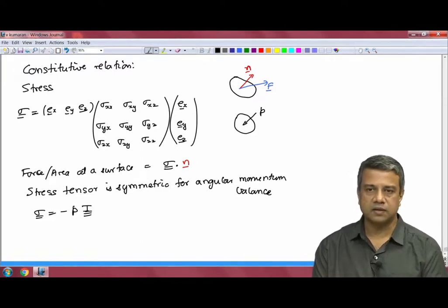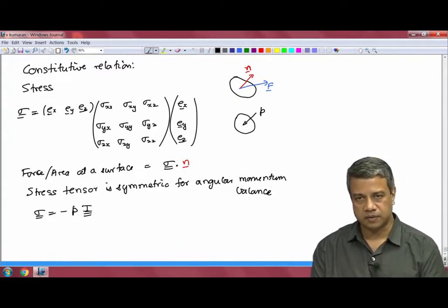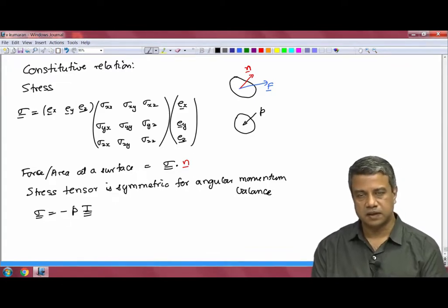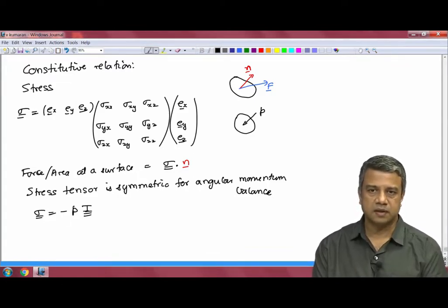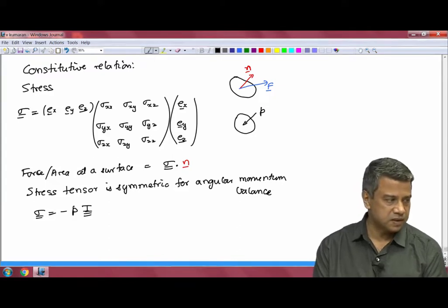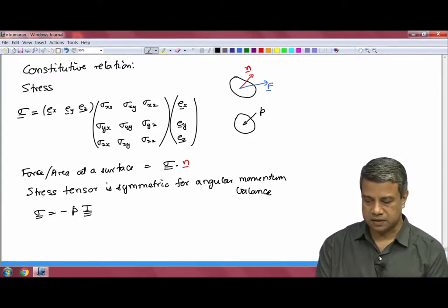Pressure is a scalar uniquely defined at each position. The force on the surface is equal to minus the pressure, and it acts along the perpendicular to the surface, and therefore, the force depends upon the orientation of the surface. The pressure is independent of the orientation of the surface.